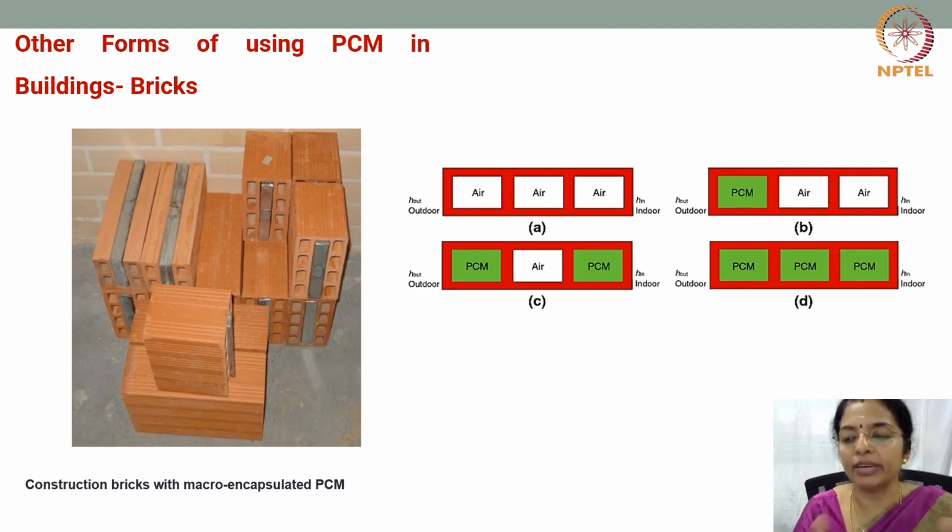We can use it more like an element with a curtain wall, and both sides can be protected by toughened safety glass. This system can extend from floor to ceiling, and it can be mounted a little behind the actual facade. Now, this system using PCMs can also be part of the opaque walls.